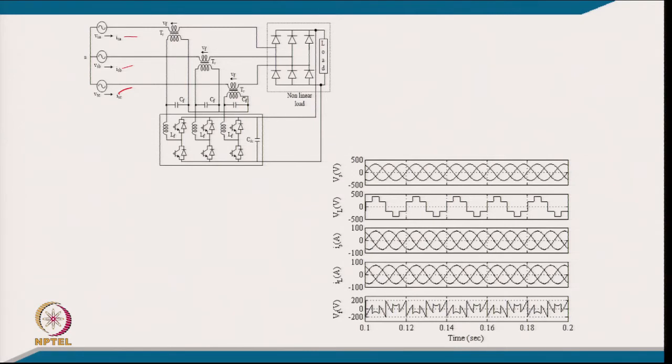That is possible only by injecting appropriate voltage and forcing this current to flow in all the 3 phases, and this capacitor or the power is fed to the load with the sine wave current through the diode rectifier. Since we are forcing all the diodes to conduct in all the 3 phases, certainly the voltage of the DC link gets reflected on this AC side. So, after making the complete model of this system with the data given in the column, the whole system is simulated and these are the waveforms which we got.